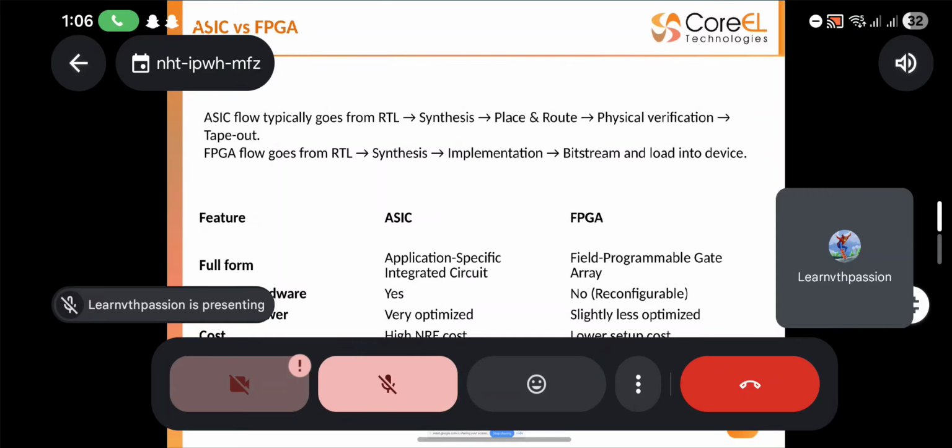And then comes the parasitic extraction. So PEX will extract your resistors, capacitors, coupled capacitors, whatever is utilized, and it will show how many, and a SPICE file will be generated. In the beginning, once the design is done, you will perform the simulation, which is the pre-layout simulation. And once the layout is formed and GDSII is generated, you can do the post-layout simulation. It's not necessarily required when it comes to the academic part.